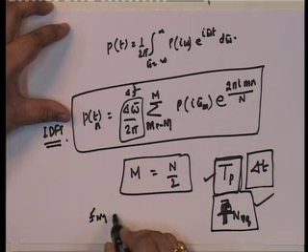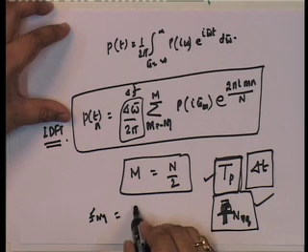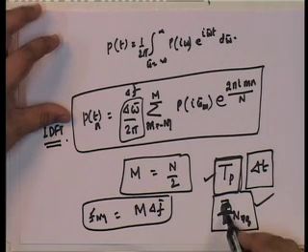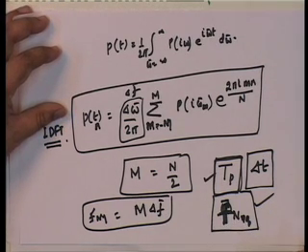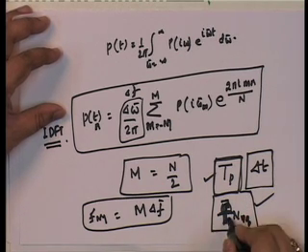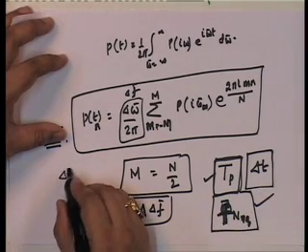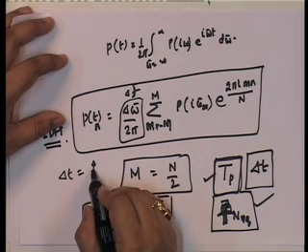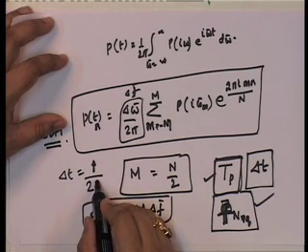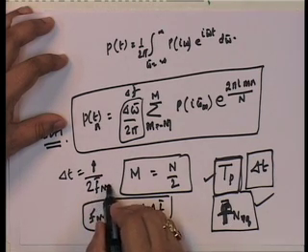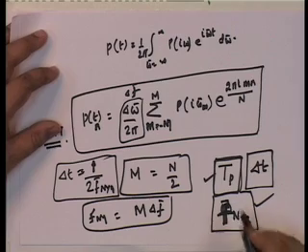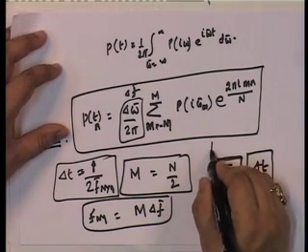f Nyquist is equal to m times delta f. Okay. So, these are the Nyquist frequencies. As I said, 50 hertz, 100 hertz, this is something that I know. This is something that I can define. If I define this, automatically delta t becomes equal to 1 upon 2 f Nyquist. This is something that delta t we know. Once we know delta t, I can find out n.